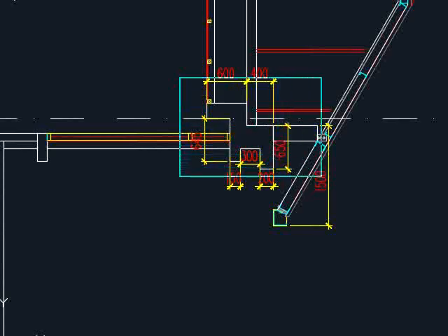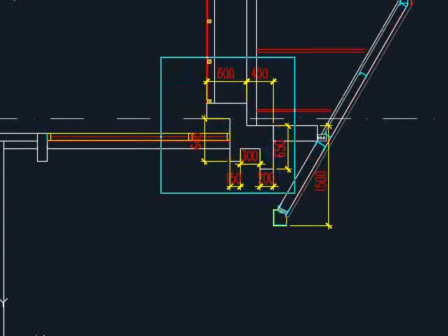The shape may be quite awkward. As already given by the architect, you have to find your way to reinforce it. You cannot simply increase the depth of the dimensions, as this may clash into the windows. The window frame and the door frame is something you cannot compromise. You have to be careful with that.